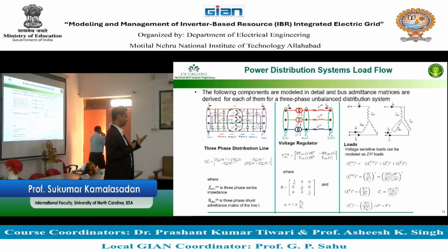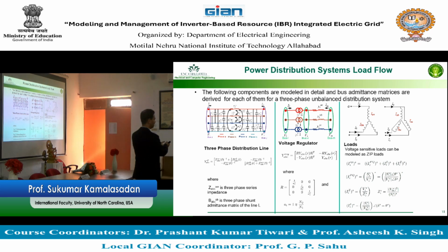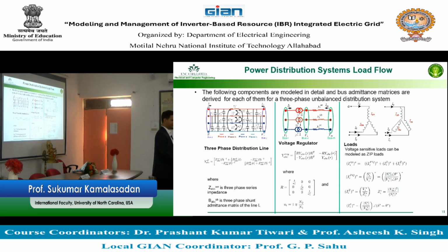That's called a three-phase transformer. So you buy a transformer from the market, you may get all the windings connected, all the three connected together. It's called a three-phase transformer. If you have independent transformers and you are asked to connect them outside, that's called a single-phase transformer. So you can represent a single-phase transformer multiplied by 3 on all the three phases. If you do that, you will be able to see configurations like this.